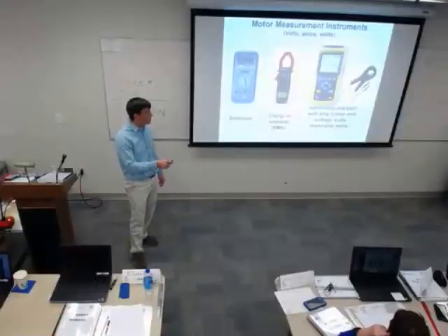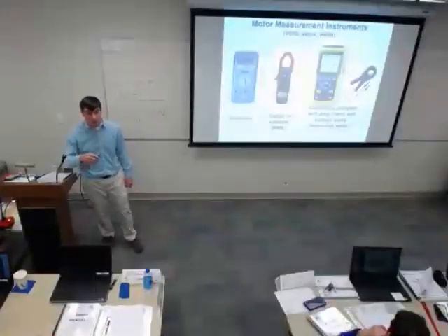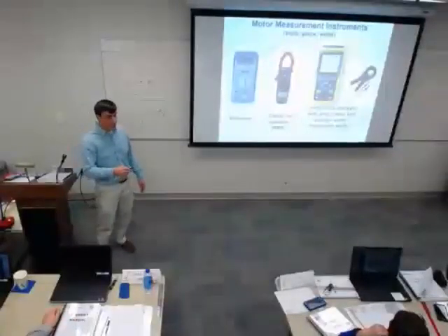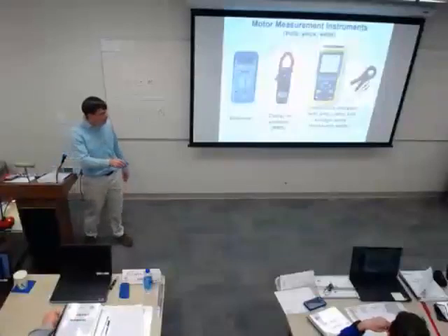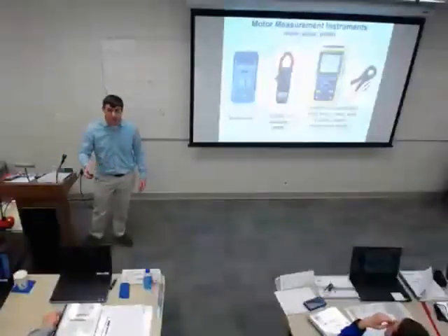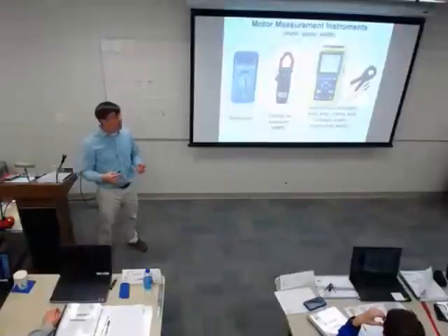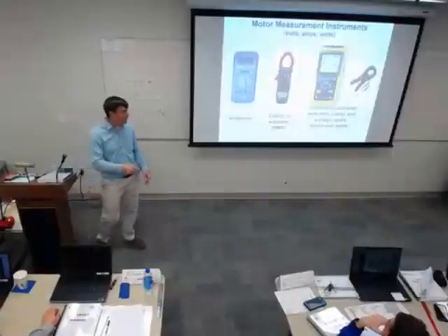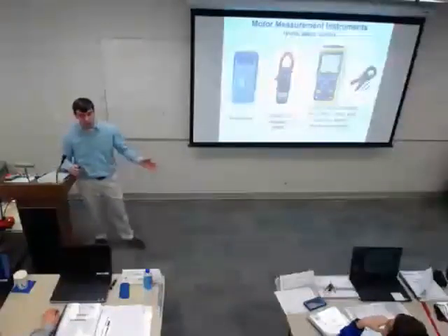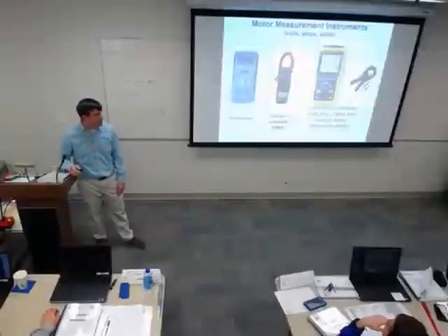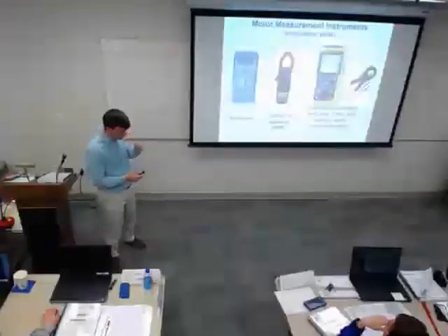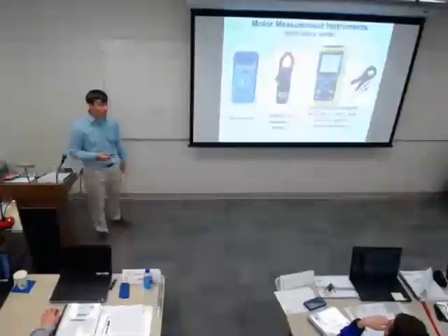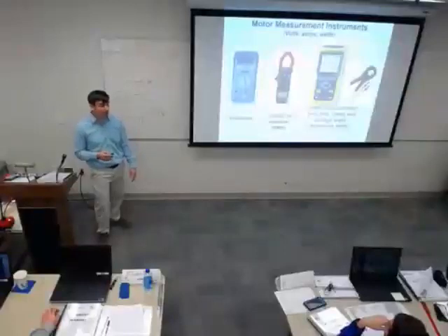Unless you're getting into some significant problem or having to do some sort of electrical capacity test on a big chiller or a cooling tower, you shouldn't need to know exactly what your power is to see one of these on your job sites, but you might. We had an example where not only the HVAC, but dryers in a barracks kept tripping the breakers for no known reason. They brought one of these out, I brought an oscilloscope out, and we figured out we had to put some kind of filter on that leg. It's the only time I've ever seen one. Yeah, if you've got some data center where your power is critical, you might need to have that.